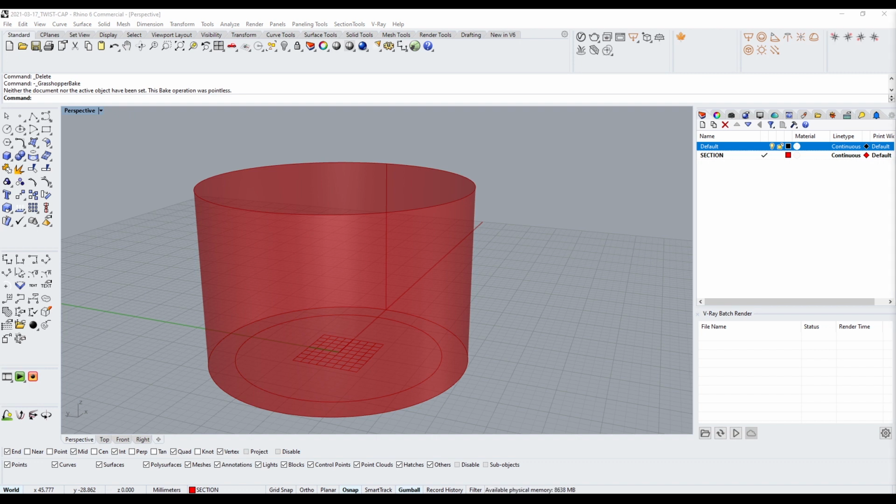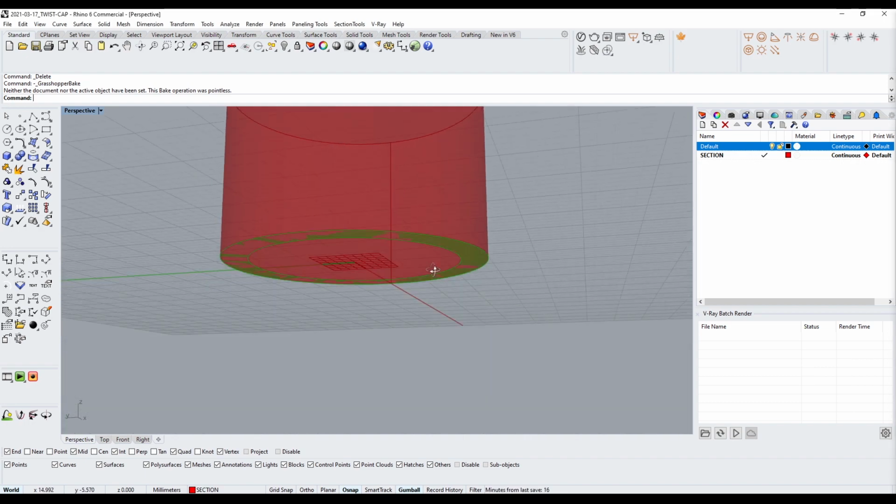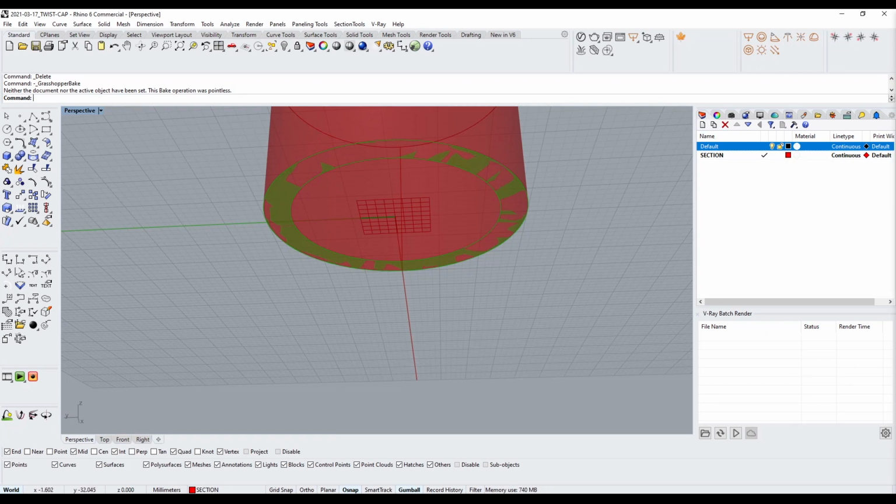So basically doing the same thing that we did to the cap, but now we're doing it to the inside. So let's go to boundary surfaces. And what I like to do with boundary surfaces is I always just flatten the input automatically. Let's go to reverse here, as long as it's more than one. So for now, there we go. We have this bottom one. And now, instead of this surface being what we extrude, we'll actually replace this one with this one.